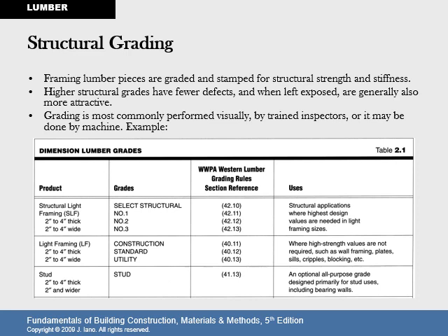So you can get number one structural, and you're going to pay a higher price point for this grade, for structural applications where the highest design values are needed in light framing sizes. Light framing typically utilizes the grades of construction, standard, or utility. And finally, the wood stud, an optional all-purpose grade designed primarily for stud uses, meaning it's going to be covered, so its appearance is not the most important aspect, including load-bearing walls.